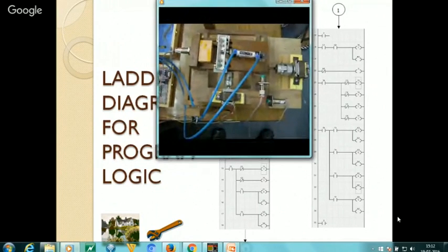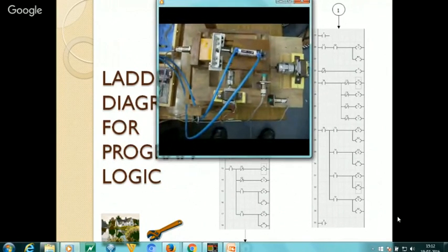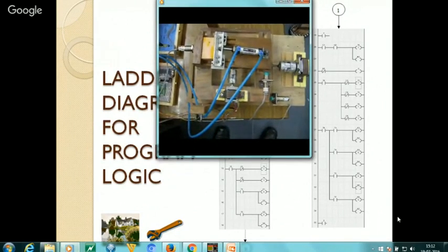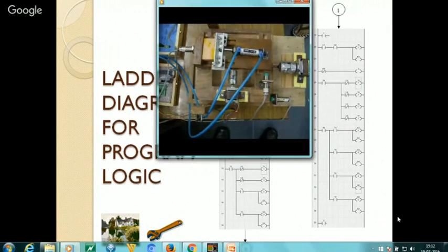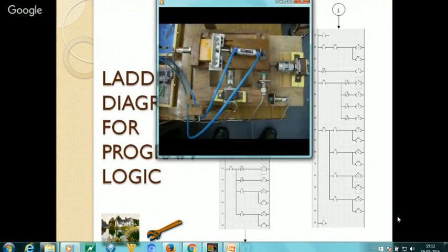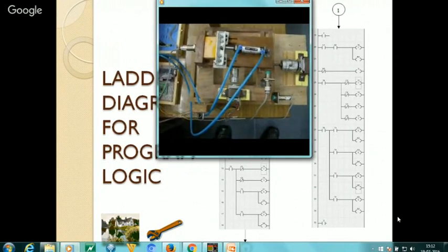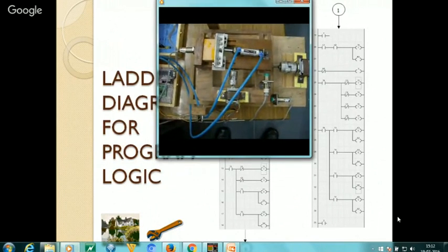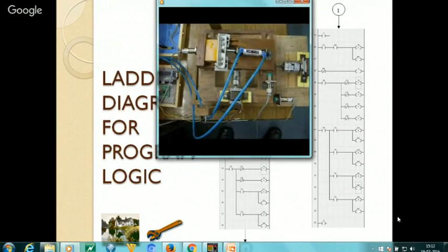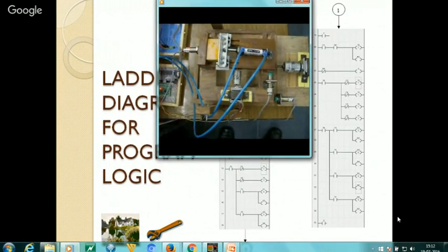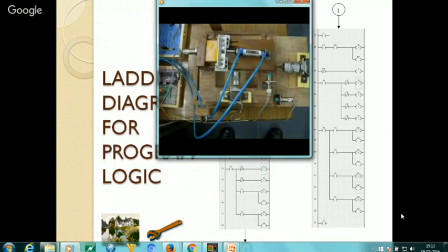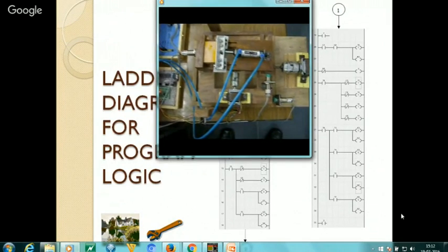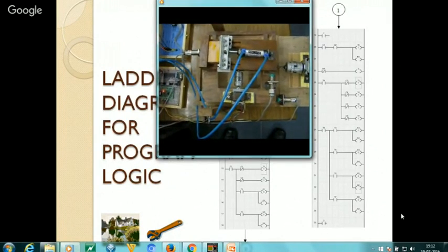So when the object is placed, there is a time delay, and after the time delay, the jaw will hold the workpiece, and then appropriate motion is given to the motors to position the workpiece. So now the stepper motors are moving in each step through 72 degrees, and thereby moving the slides through 0.26 or whatever linear displacement is there.